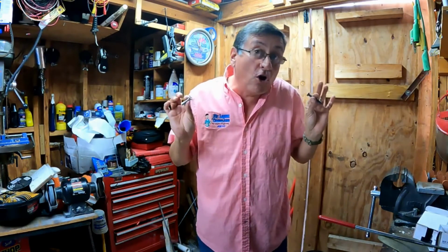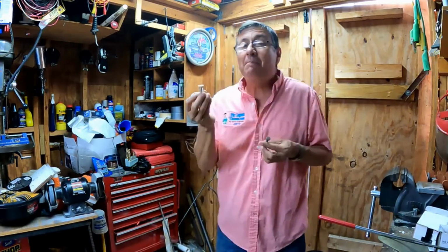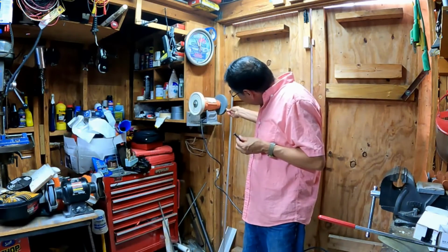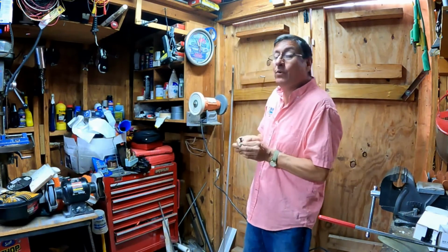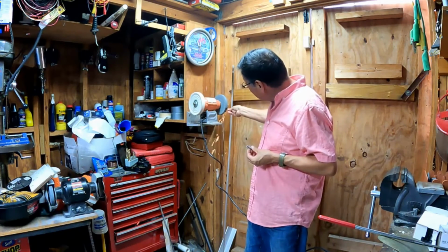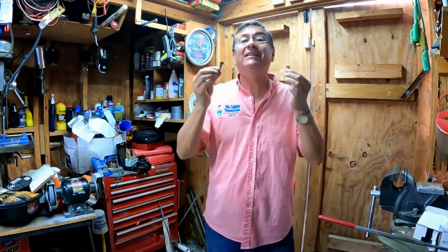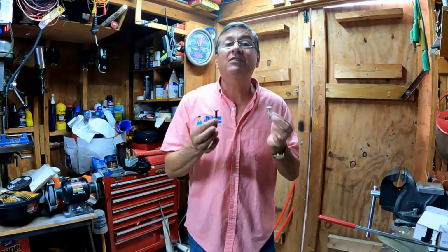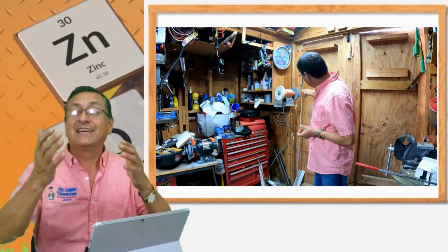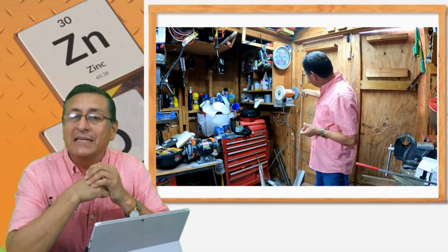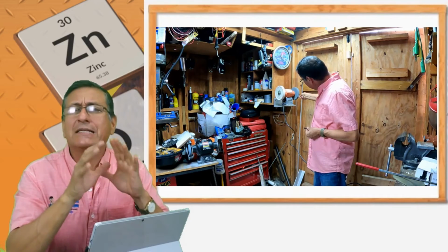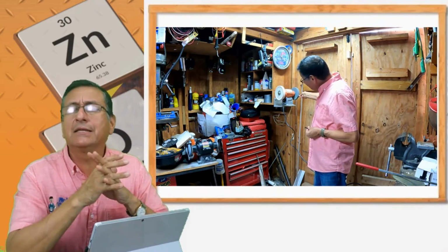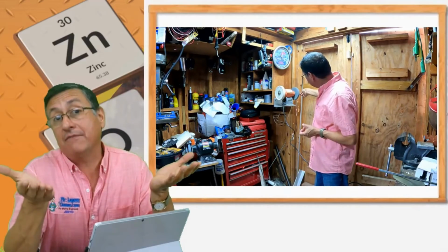A little, of course, because it has iron, but it's little in comparison with this. This is another way to identify if the steel is appropriate for a marine environment. Yes, the spark. A good stainless steel, marine grade, produces practically nothing. A little spark because it has iron.